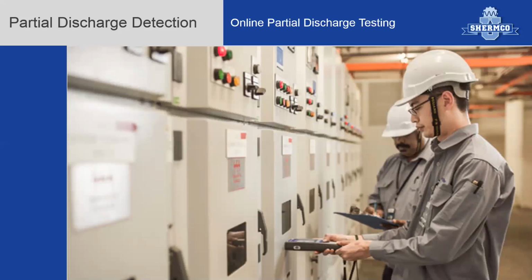All right, let's talk a little bit about partial discharge detection. Online partial discharge testing methods offer the opportunity to discover potential problems under normal operating circumstances. The online approach is a non-invasive, non-destructive, predictive test procedure. These tests can be either periodic scans in order to obtain a quick assessment of your assets and the insulating systems. They can be short-term monitoring over a longer or extended period of time to provide more accurate assessment over changing conditions, or they can be continuous monitoring to analyze assets during day-to-day operations in order to detect deterioration or a raise of alarm or call to action if partial discharge activity reaches certain critical levels for certain devices.